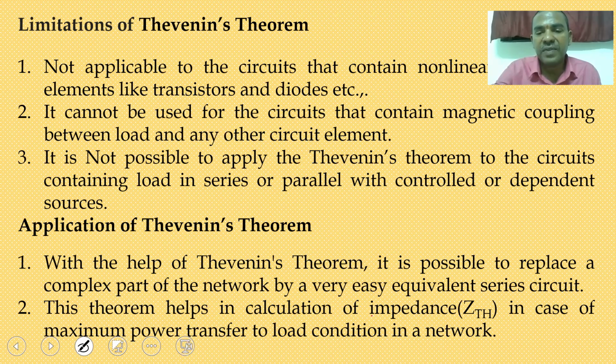And second, once the Thevenin's equivalent circuit is calculated, you can go for the maximum power transfer theorem also. With respect to any complexity of the network, if you reduce the entire network by using Thevenin's theorem, you can go for further calculations with the maximum power transfer theorem for power calculations.